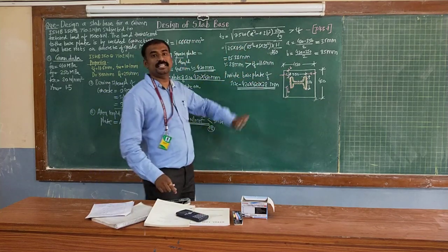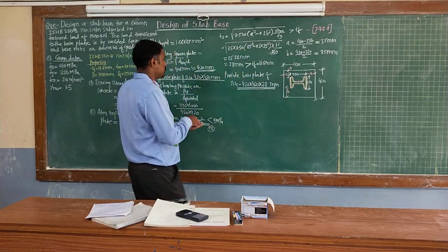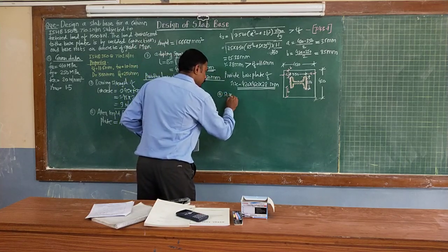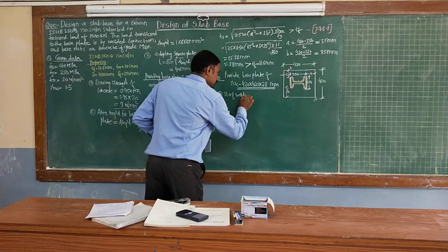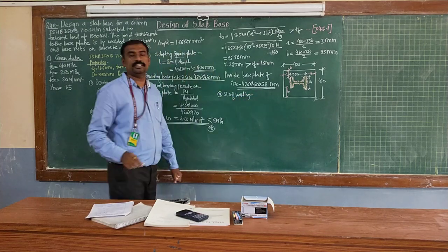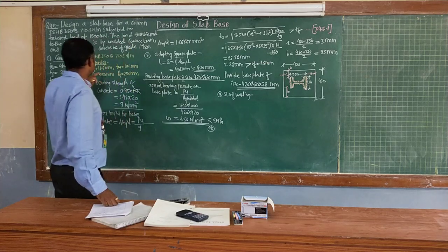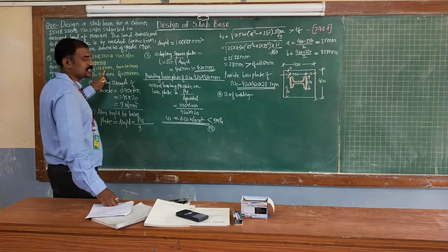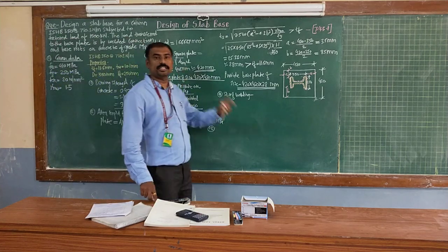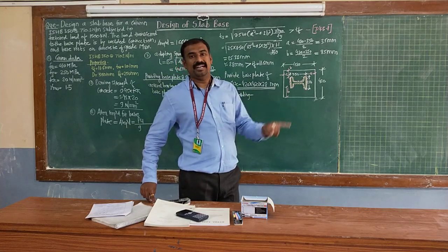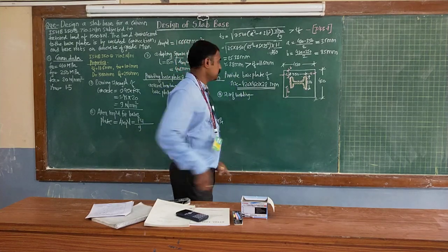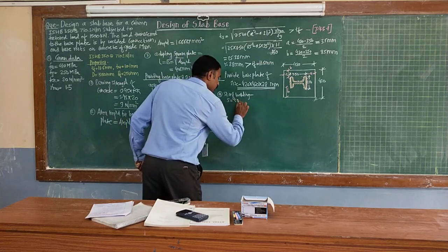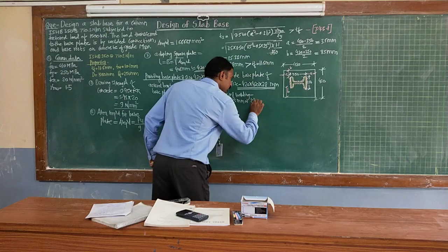So here you need to initially design the size of welding, correct. So next step, third step and fourth step, size of welding. Now for size of welding we require the thickness of the thicker part, and we are going to consider the thickness of web and thickness of flange. So the greater between these two is 11.6, and according to the table, when your thickness of thicker part is between 10 to 20 mm, your size of welding should be 5 mm, correct.